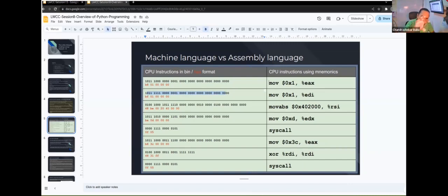You say 0th location, what is it? First location, what is it? Second location, what is it? Third location, what is it? The job of the execution unit, it works with something called an instruction prefetch unit, which will coordinate with the execution unit and say, okay, which is the next set of instructions to fetch from RAM? It will fetch that instruction. The execution unit will basically look up what instruction it is.